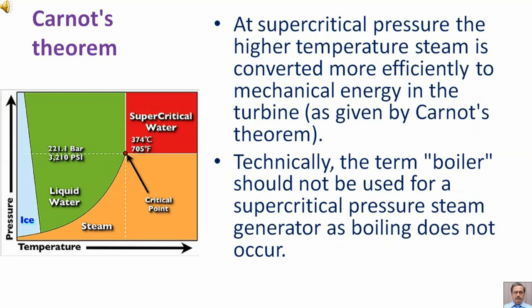At supercritical pressure, the higher temperature steam is converted more efficiently to mechanical energy in the turbine, as given by Carnot's theorem. Technically, the term boiler should not be used for a supercritical pressure steam generator as boiling does not occur.